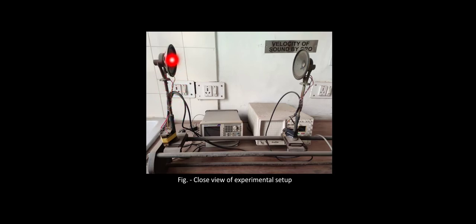This loudspeaker will generate an audio wave which travels through air and is received by this loudspeaker, which is used as a microphone, and this will convert it into an electrical signal. And here we have used an impedance matching transformer, which is connected to the y input of the CRO. So we get maximum y input.